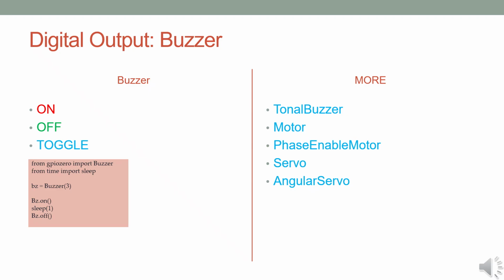The buzzer object makes it simple to manage sound output with just a few lines of code. Beyond buzzers, GPIO also supports objects for controlling various actuators, including DC motors, servo motors, and other types of motor drivers. This is all made possible through a concept known as a composite signal, where multiple GPIO pins are grouped and defined as a single device object.